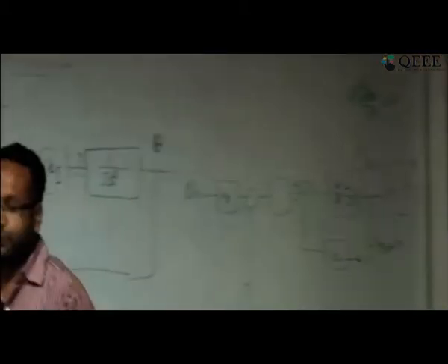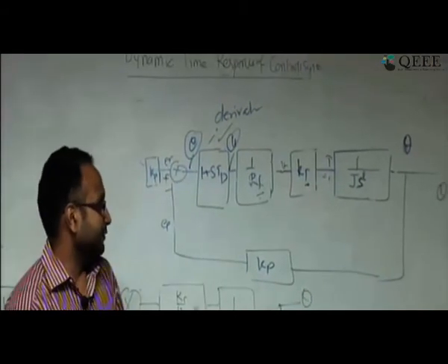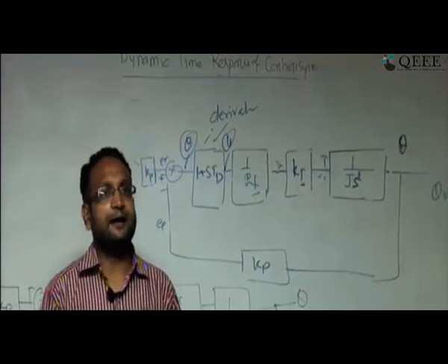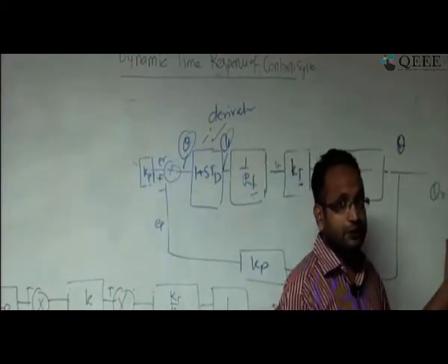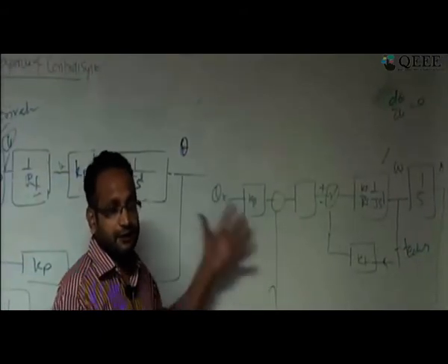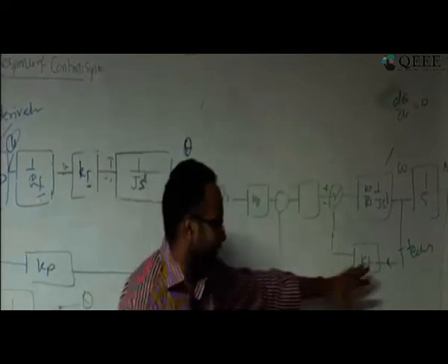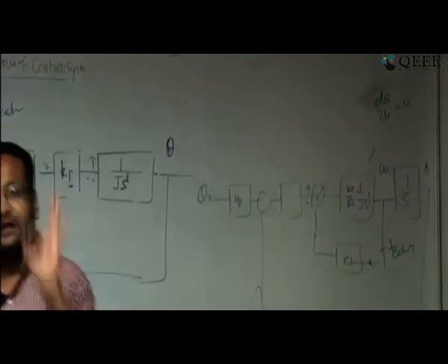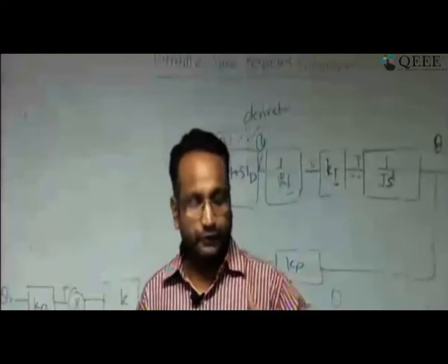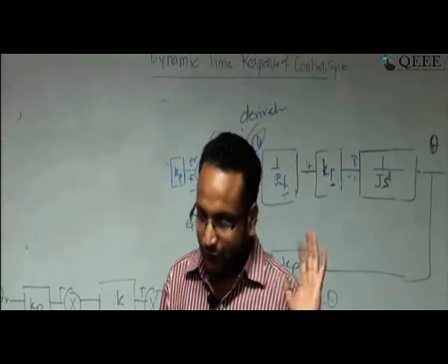This is the solution. People have talked about it when they want to use this derivative controller concept. As we mentioned, with the derivative controller we have to worry about the error, and that error should not go in. This is the alternative diagram. Please note that this solution is not feasible everywhere. This was feasible only in the case of this position control servo motor system. That's why you can see several places where they use this feedback path. This is not a derivative controller. In this you are controlling your signal where, in your feedback path along with error, you are using the derivative of the output.